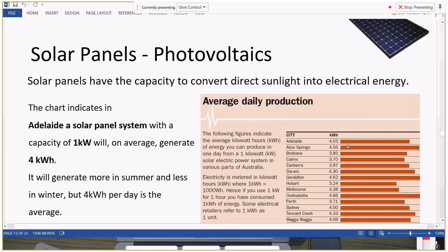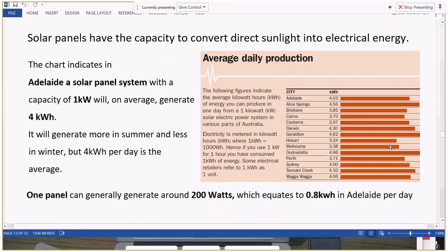It produces 4 kilowatt hours. So it's producing 40% of its potential kilowatts if we had 100% solar radiation. That's for Adelaide. If we're in Brisbane, we've got a bit more cloud cover happening in Brisbane, tropical location, or getting into the tropics there. But if we put that same system in Alice Springs, for example, not much rain, not much cloud cover there, we get more solar penetration for it. So a little bit of adjustment has to happen.